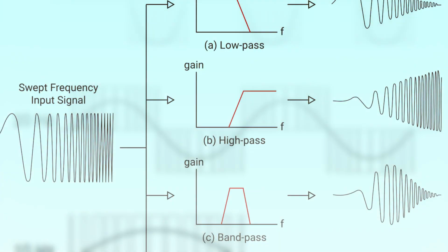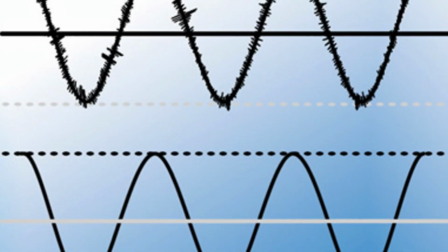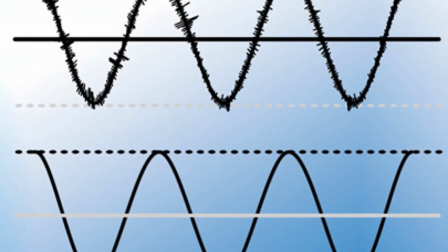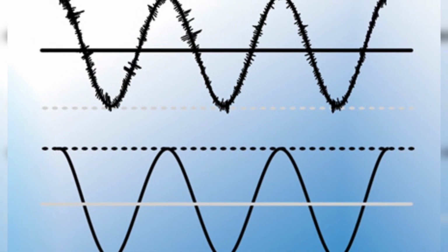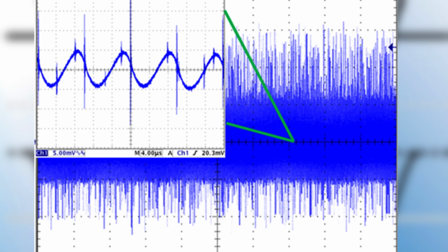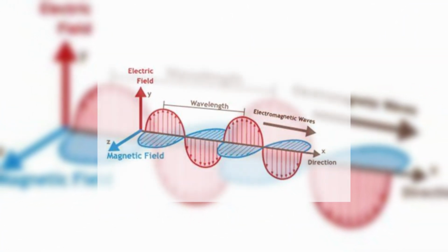The output signal is then filtered to remove the high frequency components and recover the original signal. This means that the output signal is a smooth version of the input signal, but amplified. However, this also introduces some challenges, such as switching noise, electromagnetic interference, and filter design.